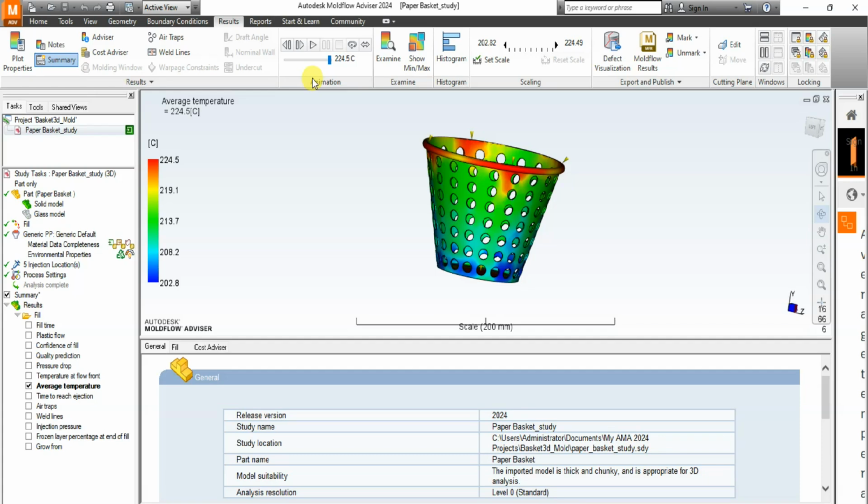Now you should also know that it is difficult to illustrate all these changes in a single display. Rather, the average temperature is used to indicate the weighted value across the thickness. Average temperature represents the energy that is transported through a particular location at a specific time. Now hotspots, which are due to excessive viscous heating during the filling stage, are indicated on the average temperature contour. So you can see this is all about temperature.